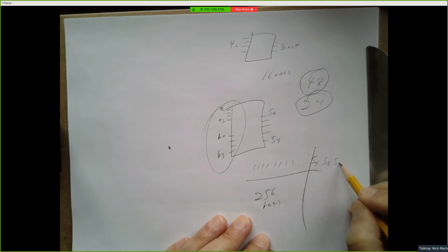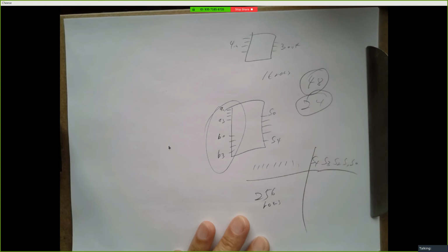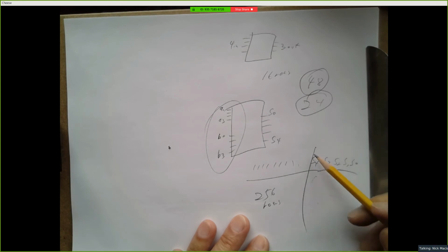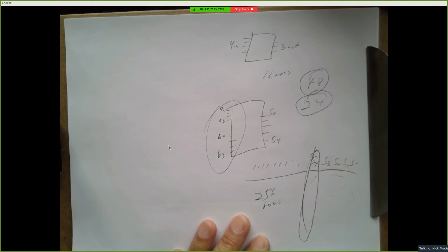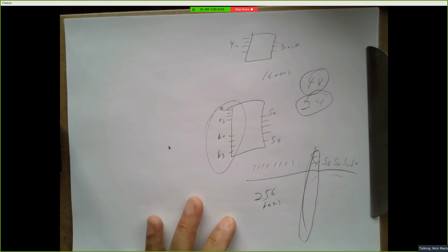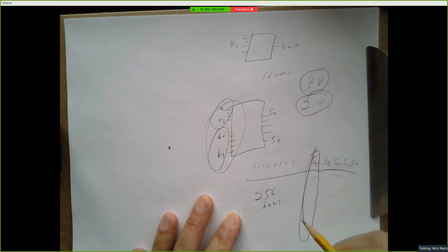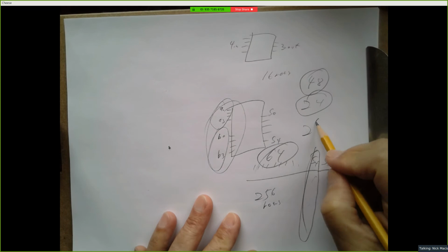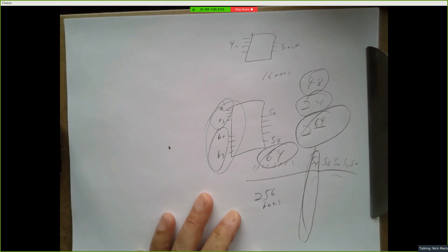And you're going to have 5 output columns. So you're going to have 1,200 plus ones and zeros in here. Each of these is going to have nominally 128 one terms, which means at least unsimplified 128 AND gates. And then a big OR gate that ORs 128 things together. Now you can do some simplification, but try to make a 32-bit adder like this. 32 bits for one number, 32 bits for another number. That's 64 input bits. That's 2 to the 64th rows in your truth table. That's crazy. 2 to the 64th is like a big number. I was going to say a billion, I think.